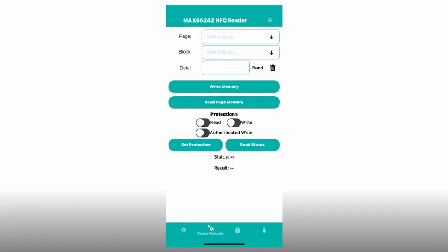So the next function is called Device Features, and this is about non-SHA-2 based reading or writing to the 4K bit EEPROM array that the MAX 66242 provides. And that 4K bit array is partitioned into 16 pages of 32 bytes. Each of those pages can have a protection setting that this particular function we're looking at here can apply.